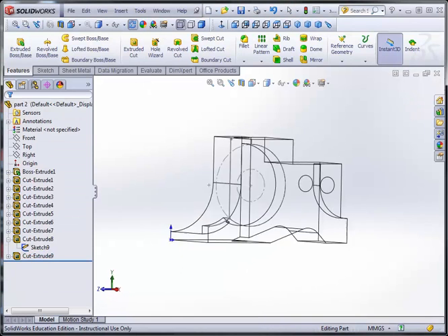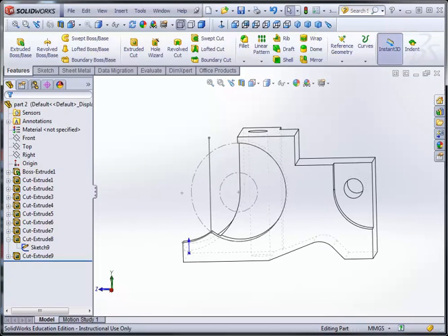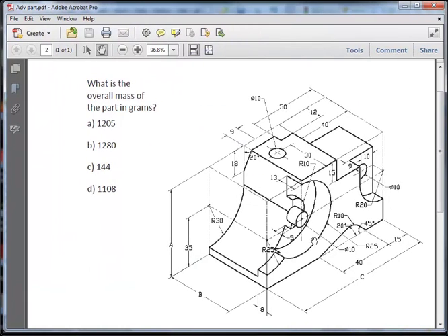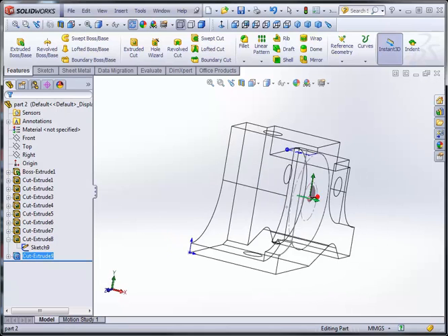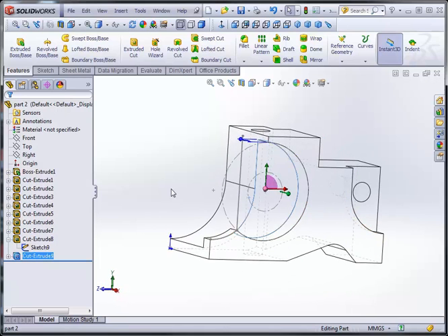Now we'll go back to our sketch, and now what we will look to make are these two boss extrudes. First this one and this one. This one is at 5 and the other one should be up to surface from there. So we will select the face here. Why this one matters is because we don't want our extrude to begin on the surface.